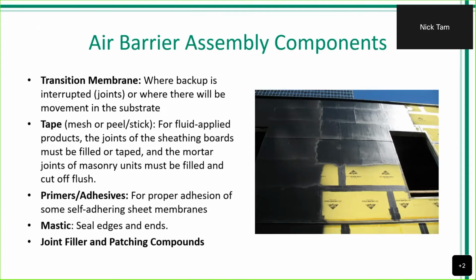And for patching compounds, you think about a sheathing wall meeting a foundation wall. Well, with that concrete, if it's not going to be very smooth, we have to make sure that this membrane can adhere to it, right? This is where those patching compounds will come into play, and we smooth out the surface so that we can make sure that these membranes have 100% bond and there's nothing jeopardizing that bond.